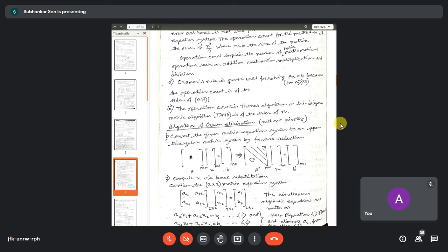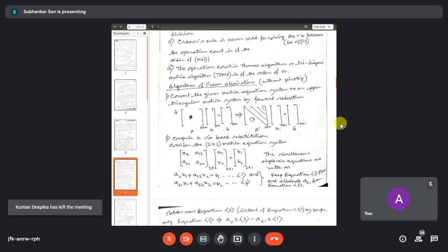So let us first discuss this graphically. We are showing the algorithm for a matrix. It need not be sparse. It can be a dense matrix, or it can be a sparse matrix. After implementing the discretization, after all these steps, you are coming here. You are getting the Ax equals B system, where A is the matrix of the known terms. In a linear equation system, this A is not a function of X.